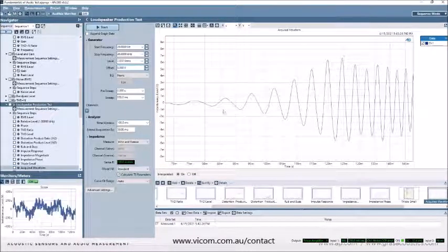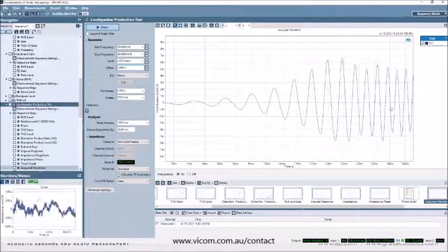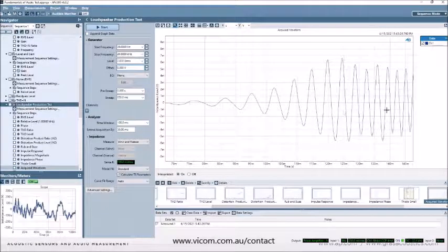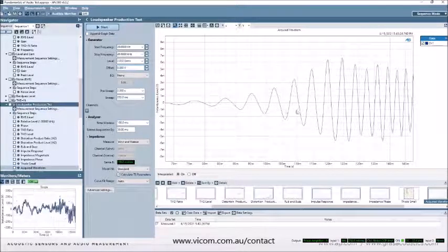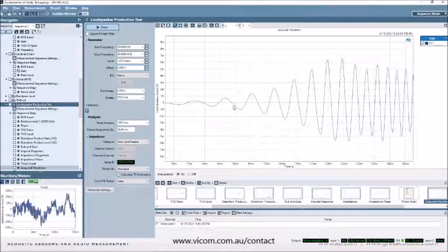It might not immediately jump out at you, but here at 70 milliseconds, the frequency of the signal is lower than it is here at 140 milliseconds. You can see the distance between the sine waves is closing. The frequency is increasing. And what's interesting about a log chirp is that it is increasing continuously. Every sample representing this waveform is at a different frequency than the previous one.